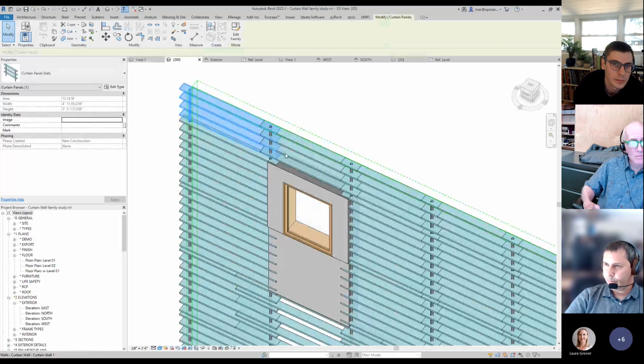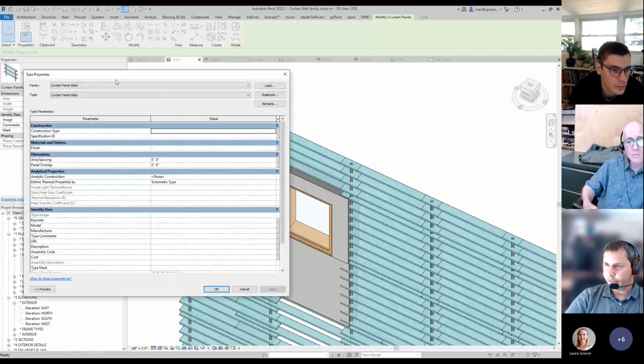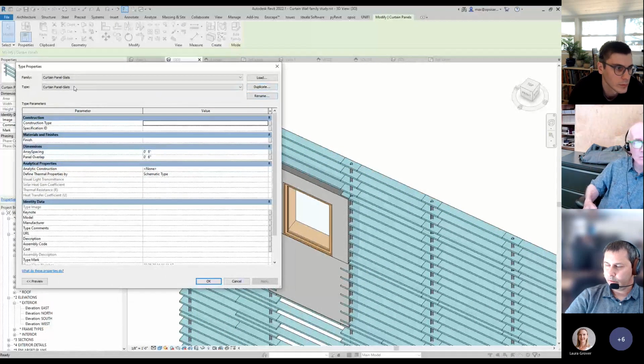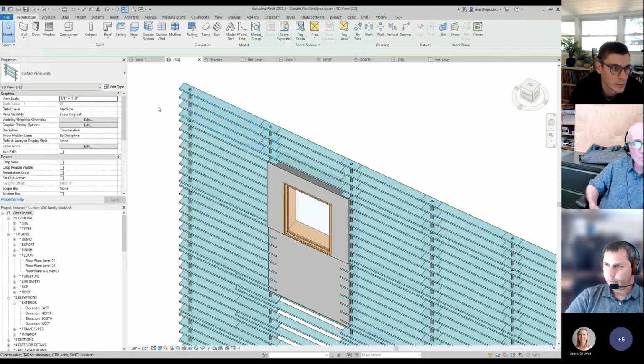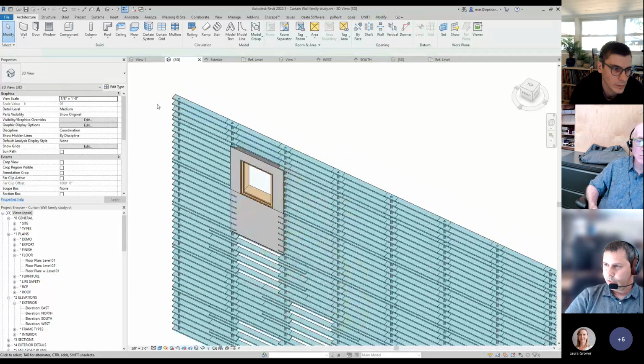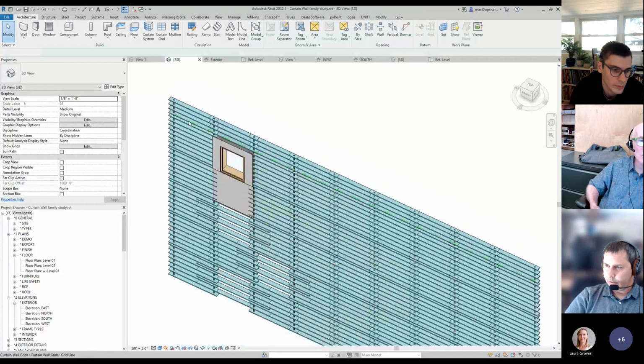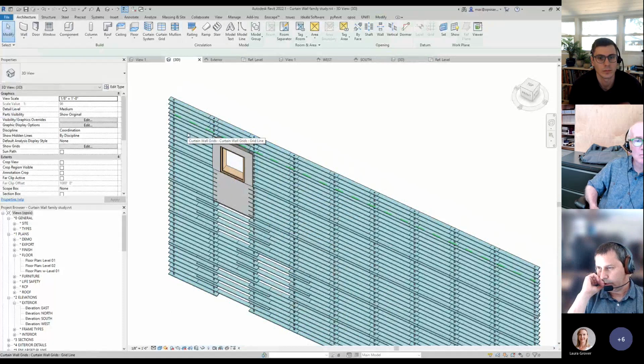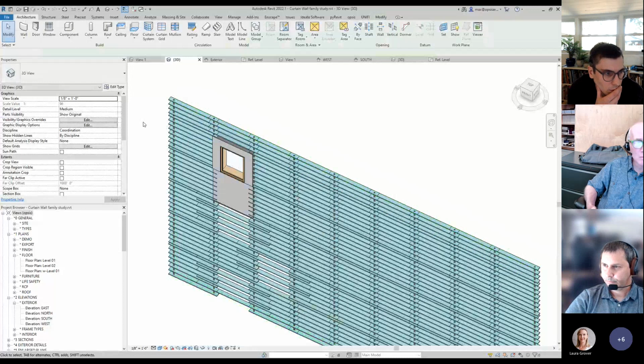And if you had a parameter, you can start to create duplicate families that have a different material type. So that's another way to use it if it's linked to a parameter itself. So I could have slats that are a certain type of wood, and then others that are a different material within that same family type.